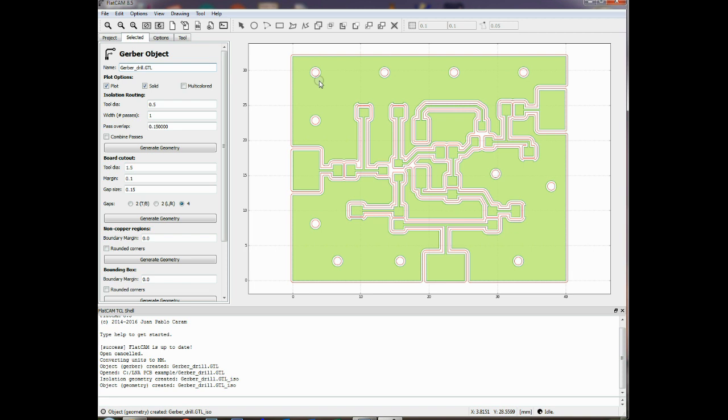If you're going to drop a hole through your copper, you'd expect the PCB design tool to put isolation relief around it. So if you put a bolt through, you don't short the bolt to the copper. So that's kind of standard practice. But in my particular case, for this design, that's not what I wanted. I don't want any relief around the hole.